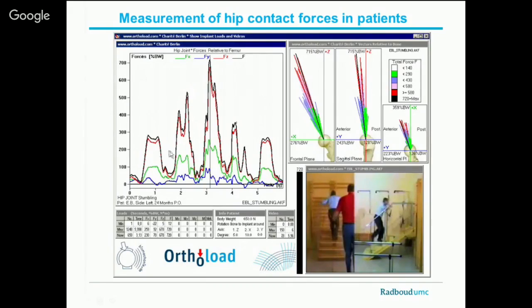And what it means in the hip contact forces is, so he's walking up the stairs and he's stumbling here, it's 7 times body weight. Whereas if we do tests on hip implants to do the fatigue testing, I think it's 3 times body weight, something like that. So you can imagine that, due to such a mild stumble, right, if people fall, then you could break a prosthesis. So there is a lot of debate now about increasing the standards of testing.